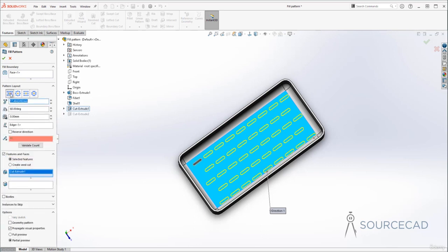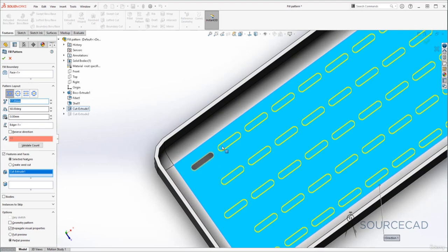We just want this kind of pattern. And here you can select the gap or the instance spacing, which is set to 17 right now approximately. Well, let's make it exactly 17. So I'll type 17 and press the tab key. Alright, so that's done. Now what is happening in this case? With this 17 units selected, the pattern gap is 17 along both the directions. From one point of this pattern to the same point on the second pattern in this direction as well as in this direction, the distance is 17.